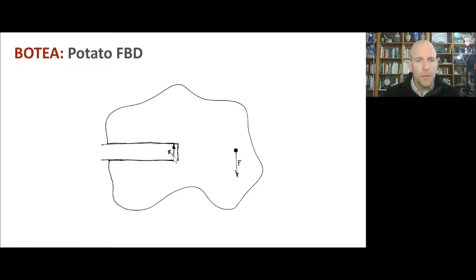Now, these two forces are offset. So we're not in static equilibrium yet. This thing would want to spin, right? It would accelerate clockwise without anything else. If we could get that reaction force right on top of the rope force, then we would be in equilibrium and everything would be okay. But we specified that this rope force has to be offset from the table by some amount to make it a little more challenging.